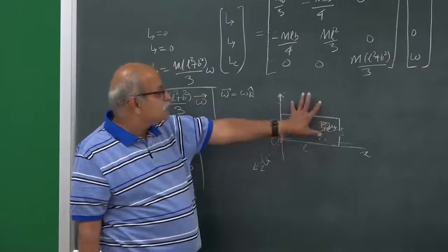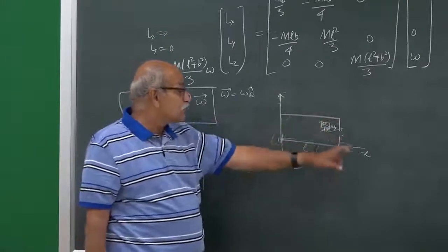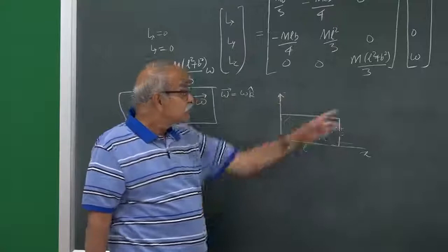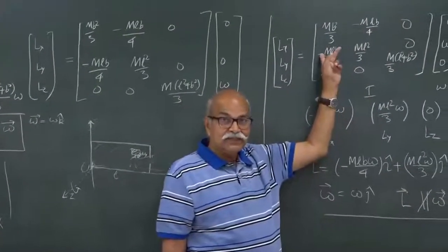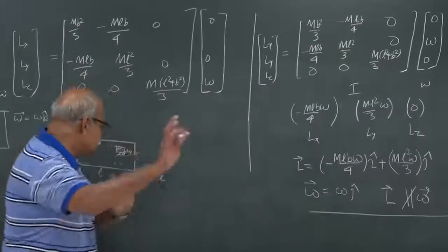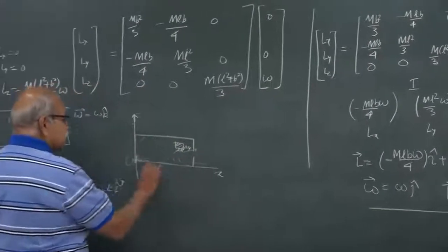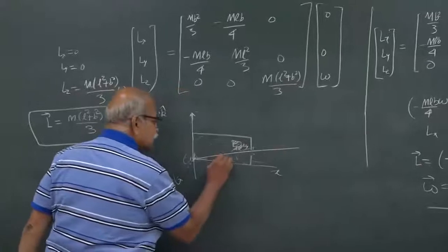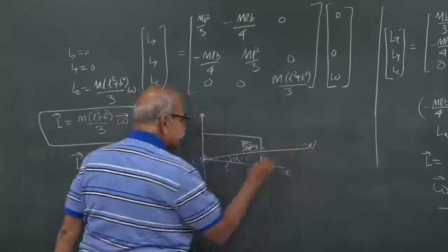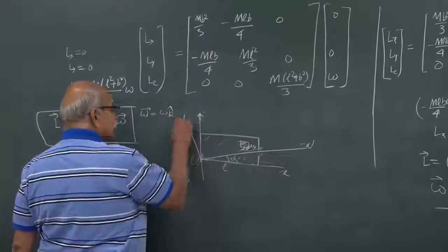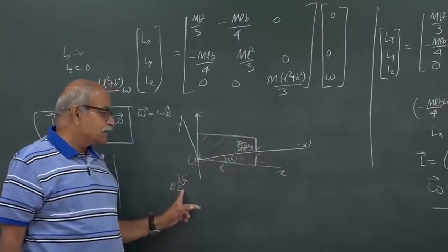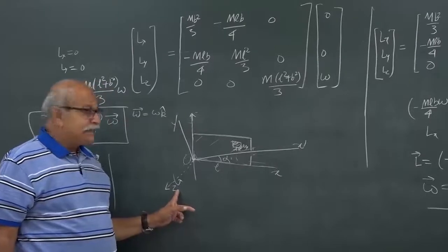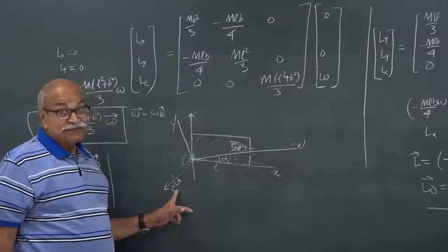They have to be in this x y plane, but these are not, because if I use these x y z, I do have these product of inertia terms. You can find that and this will be your homework. It must be in this plane. So, suppose it is at some angle alpha, this is say x prime and this is y prime in this plane. If these are principal axes, then the product of inertia term should be 0.